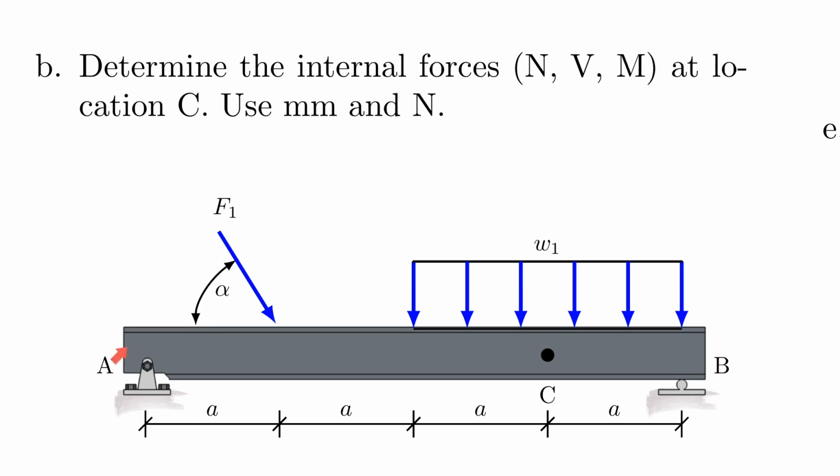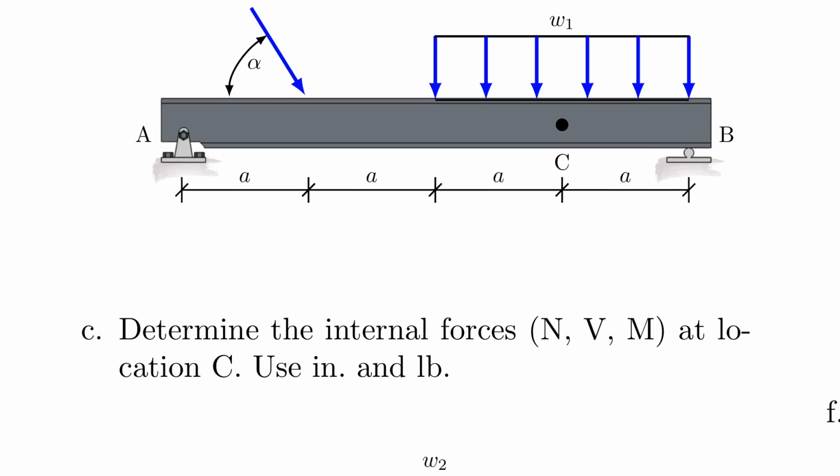However, after you cut the system, either side, you just bring in your internal forces and you calculate them like you calculate cantilever support reactions, just by cutting through the system, even through the distributed force. So don't get too hung up on this. Again, I see that sometimes in the classroom, that initially students get hung up by the fact that the distributed force actually passes over the point, but just blindly cut it off on the other side, no matter if you do the right side or the left side. And I'm pretty sure you can solve this as well, because you already solved cantilever beams with distributed forces acting on them. Let's go to the next one.